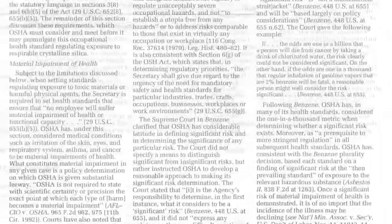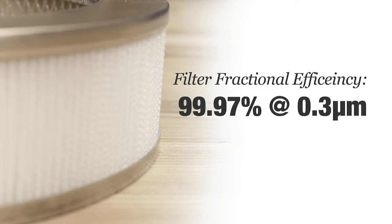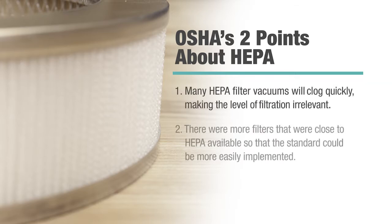Let's first take a look at what is written about filter efficiency. It shows us that OSHA had originally considered requiring HEPA filters, which provide a filter efficiency of 99.97% at 0.3 microns, because they believed they offered better protection from silica dust. However, they found two things. One, too many HEPA filter vacuums will clog quickly, making the level of filtration irrelevant. And two, there were far more filters that were close to HEPA available, so the standard could be more easily